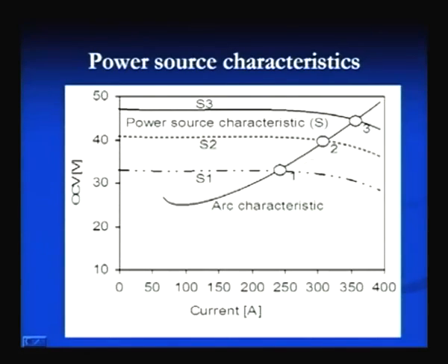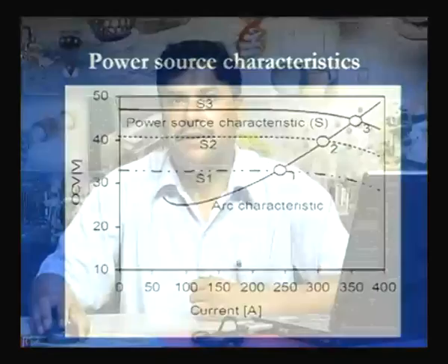If the open circuit voltage is set differently, then we get different arc voltages. In the same way, if the arc length changes for any reason, then a change in the operating point is also noticed, which affects the welding current as per the increase or decrease in arc length. If arc voltage increases, then welding current decreases, and the decrease in welding current in turn reduces the melting rate. So, this feature is used in developing the self regulating arc.